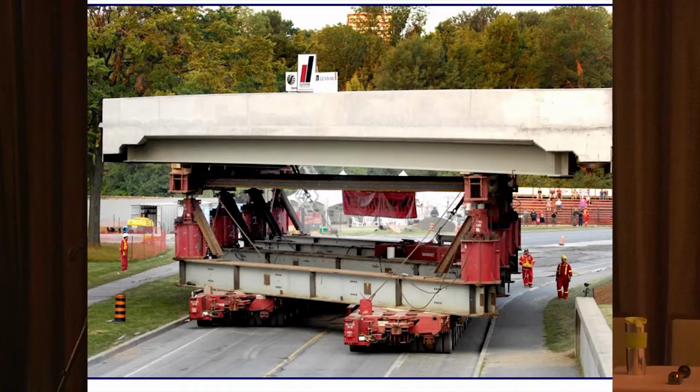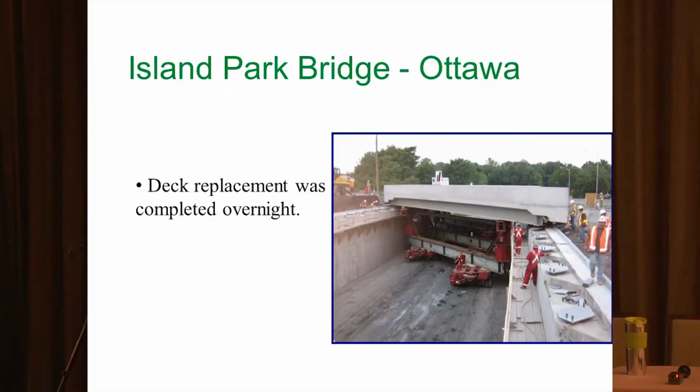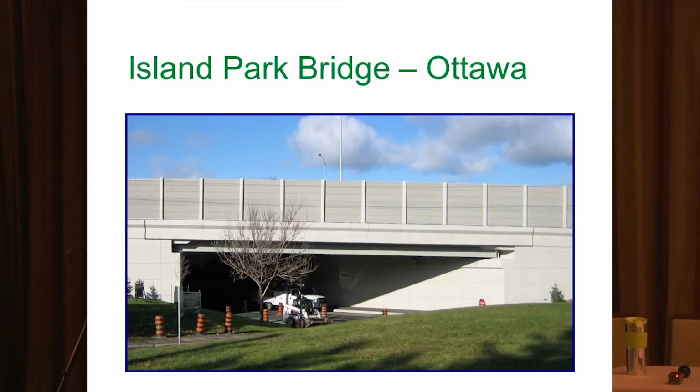They came in over a 2-day weekend and removed the existing deck. They had been just slightly off-site, pouring and putting together a new bridge. They came in with their lift system here. They took out the old bridge one night, dropped the new bridge in, replaced it, and over that 2-day weekend, they were able to do this entire project.